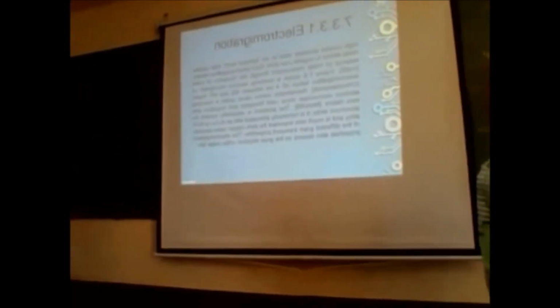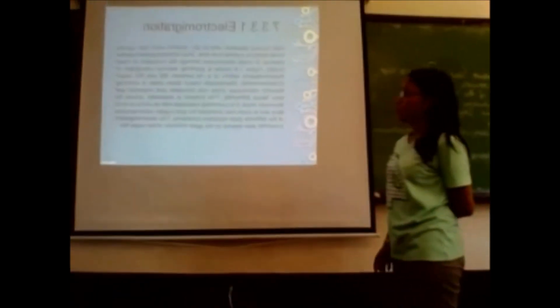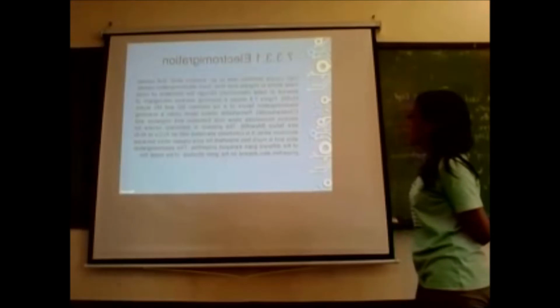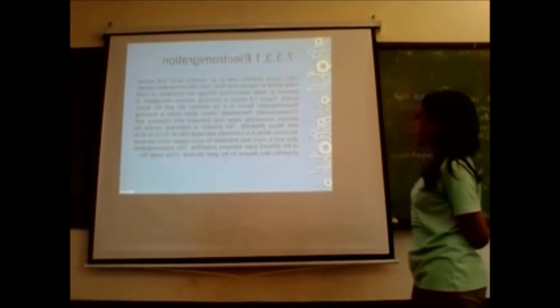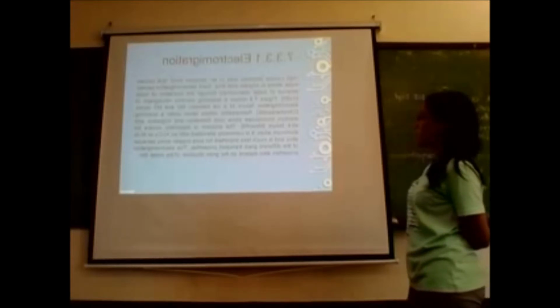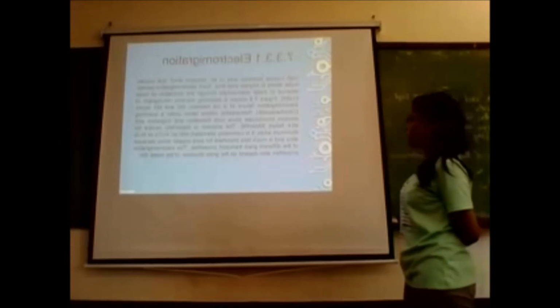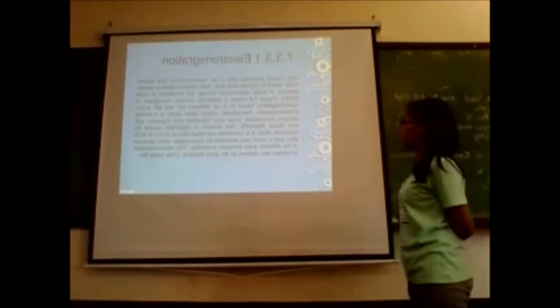High current densities lead to an electron wind that causes metal atoms to migrate over time. Such electromigration causes wear-out of metal interconnect through the formation of voids. Figure 7.8 shows a scanning electron micrograph of an electromigration failure of a wire between M2 and M3 layers. Multiple videos taken under a scanning electron microscope show void formation and migration and wire failure.